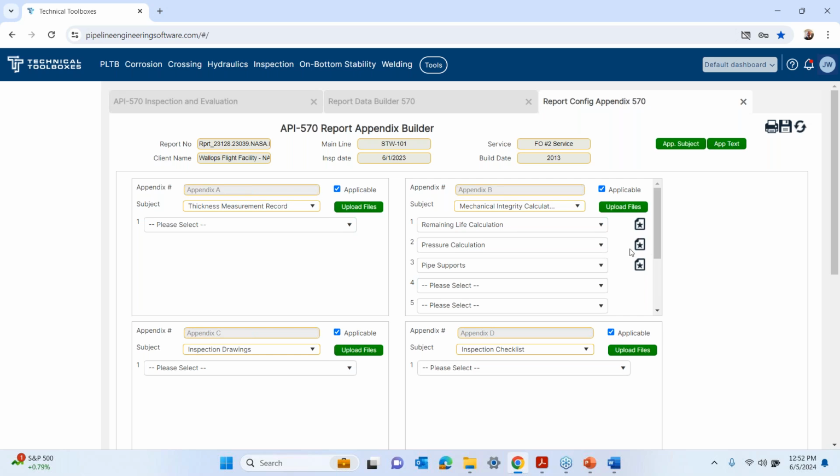But you do that calc, and then you do your pipe support calc, and that is just doing your bending moments from one support to another. Let's say you've got 20 feet there, it will calculate, based on the weight of that pipe, how thin it can be to support the pipe. So you do those calcs, and you leave a little bit more for corrosion, because at that point, that's a flag to say, hey, I need to replace that, but I need to make it to six months or a year from now when the turnaround comes up. So that's what you're after.